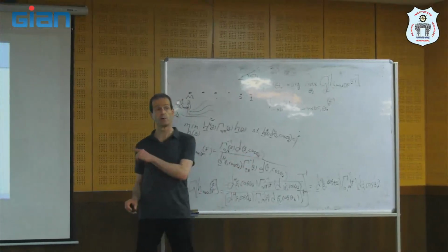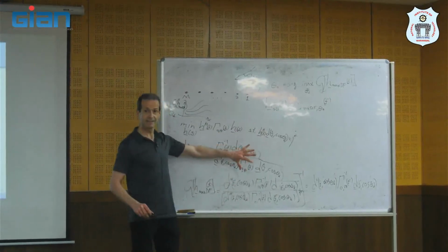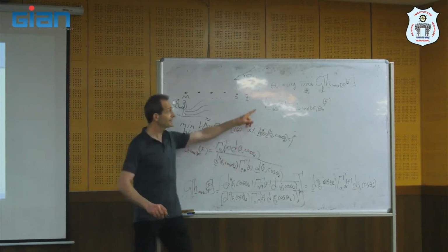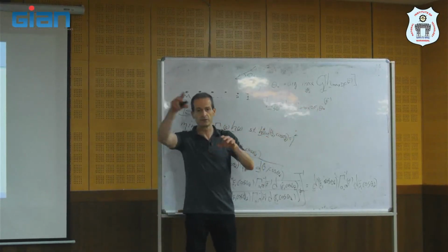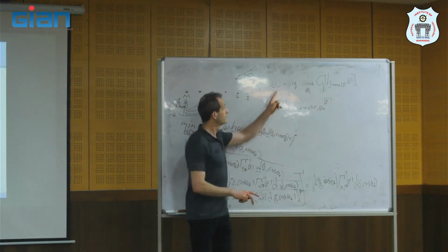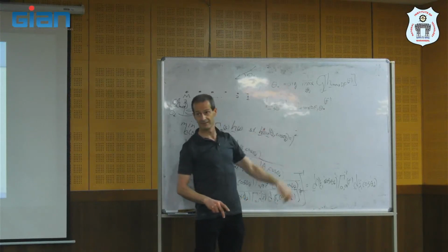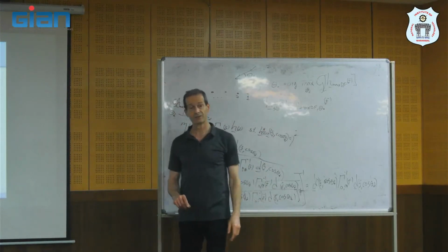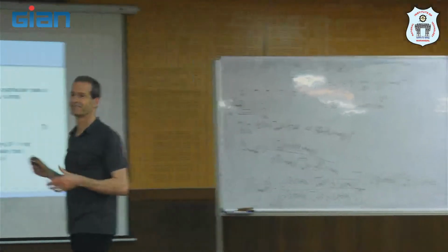But this is for a uniform linear array, because theta d equal to 0 maximizes the directivity factor. If the array is different, with different sensors, you need to find the theta d that maximizes the directivity factor. It's beautiful, right?